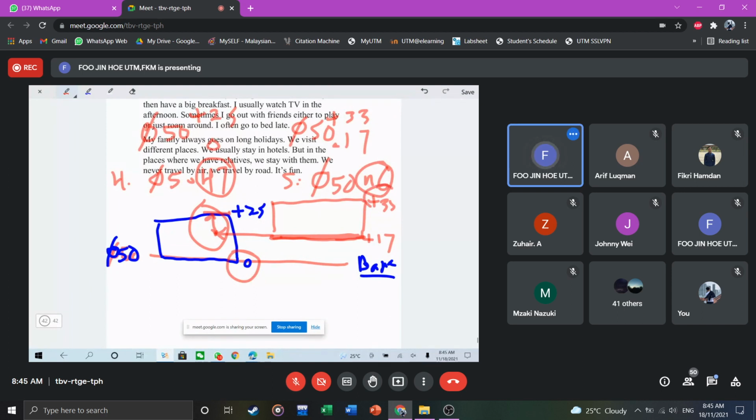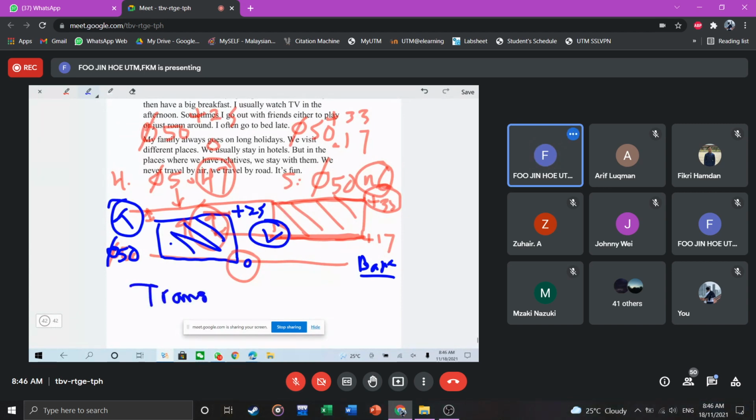okay, if this is 33, however, when we look at this, there is a gap here. So it's telling you that this shaft is bigger than this hole. So this is tight, and this other one here is loose. So it will be between tight and loose. So this will make this particular assembly become a transition fit.